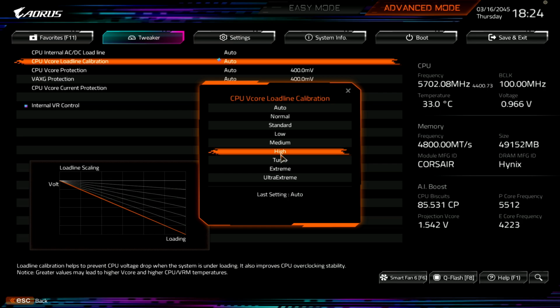But there are a bunch of other Gigabyte motherboards, like say the Z790 Elite, that use an ON Semiconductor controller. I think it uses a different load line slope. I haven't yet verified. I am actually considering making videos specific to each motherboard. But with this motherboard, the default load line setting is 1.1 milliohm for the VRM, and High is a 0.5 multiplier for that load line setting.